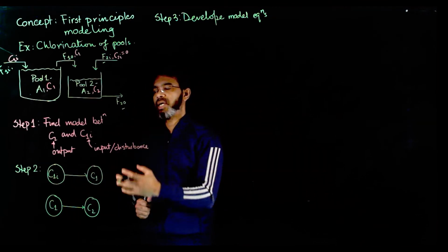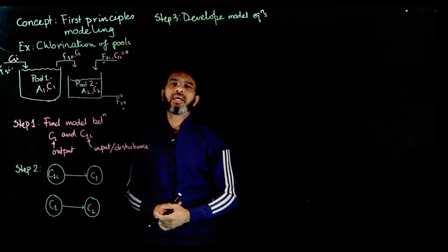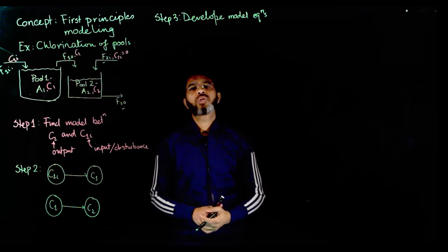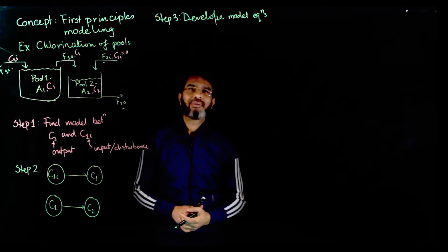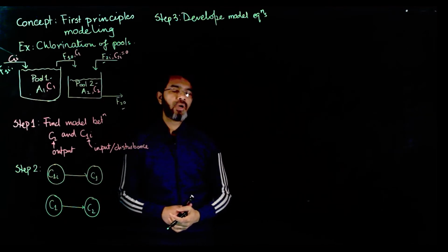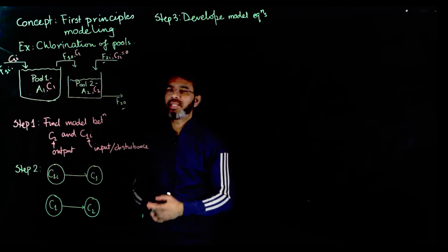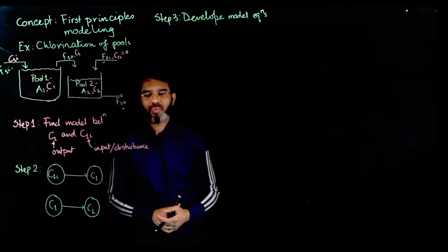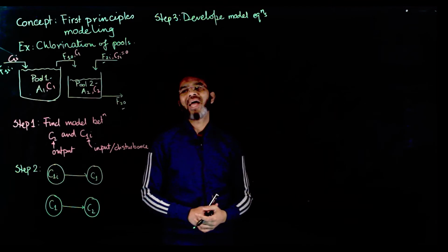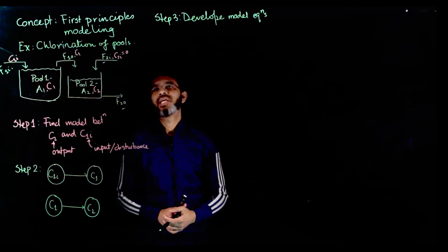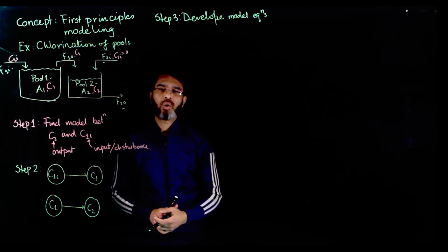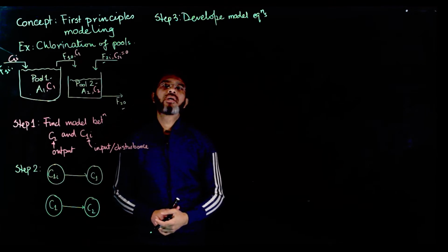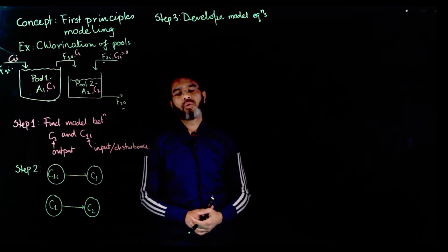We see that for this case, there is nothing regarding the temperature, so conservation of energy will not be relevant for this case. Also, we don't have anything related to momentum, so we'll discard that as well. So we're left with the conservation of mass, and for this case we see that there are two components, water and chlorine, so this component balance equation will be relevant.